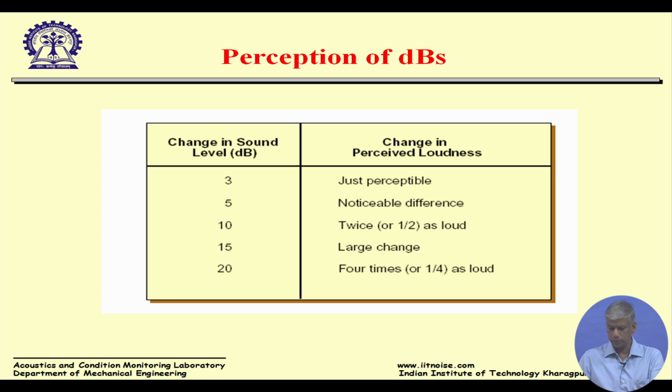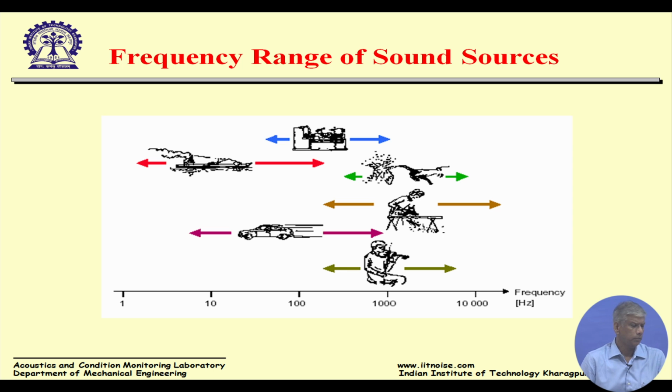So, perception of decibels. 5 dB or 10 dB. I've been to industries where the engineers are happy if you see a difference of 3 dB, but really, when you do an A/B comparison, switch on, switch off, you can only notice a 3 dB difference. But to bring in any substantial difference, it has to be at least more than 5. And of course, we have been talking about audio frequency ranges from 20 to 20 kilohertz is our audio range, but things do happen beyond 20 kilohertz in the ultrasonics and infrasonics below 20 hertz. One has to be just aware of the frequency sources.